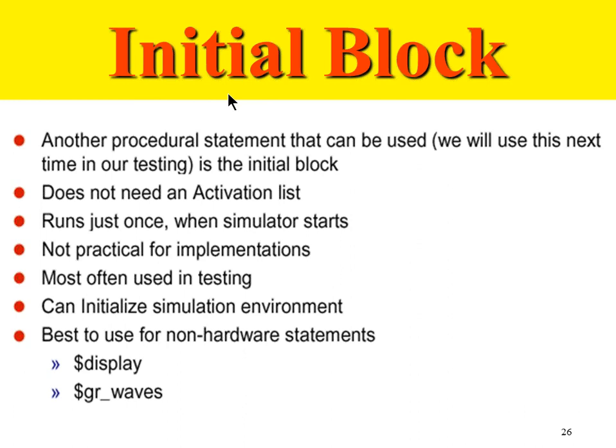So when I power up or reset my system, my memory gets initialized. Or the other option is I have to blink some LEDs to show that the board is in OK status. All that logic will go in the initial block. That's where I need the initial block in hardware. So if you want, you can just note down these couple of points and then we proceed.